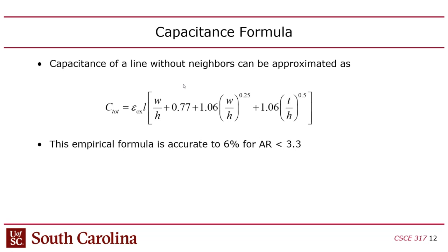In a circuit board, they have material that goes between the layers, but they can't use silicon dioxide. I'm not sure why. They used to use that in multi-chip modules, and I think they might be using it these days in these new interposers they're building. But in a circuit board, you can't put glass, basically. So they use another type of dielectric material, by which I mean an insulator material that separates the layers.